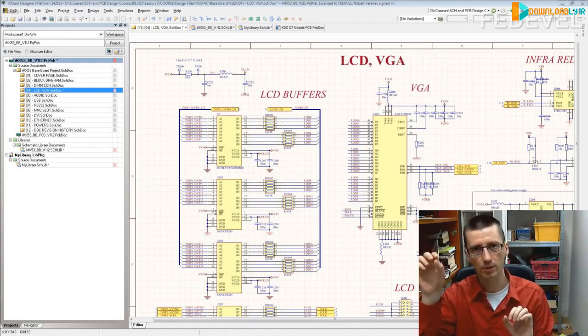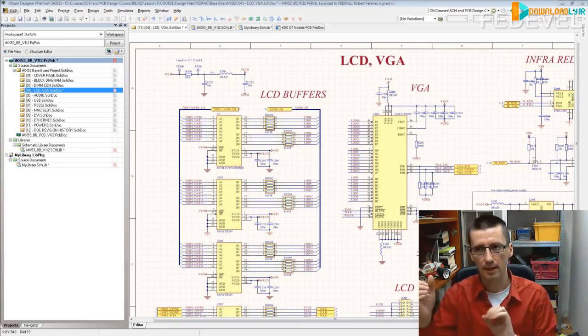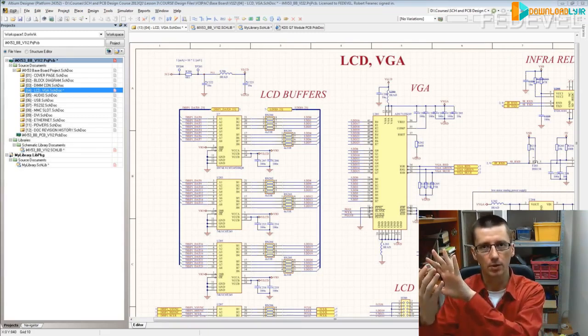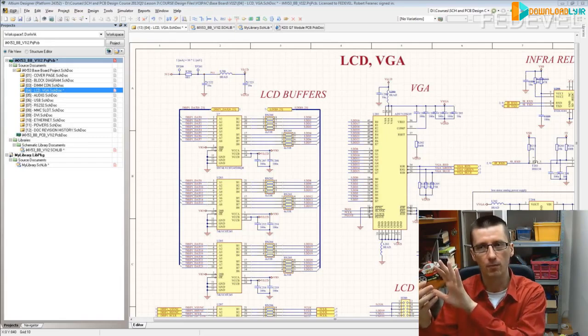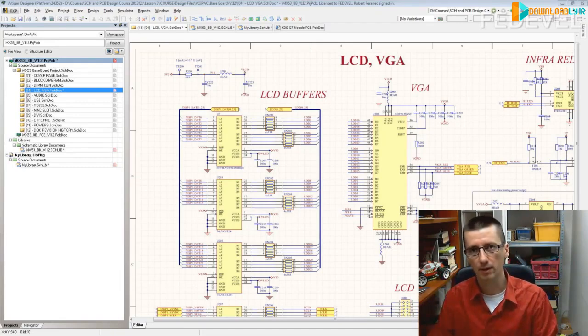I don't mix it with the digital components. And even in one of the designs, there is Ethernet on the top, for example. In another design, there is PCI Express or some other wireless cards. And audio is working perfectly, no problems. And the ground is not separated, the ground is common for the whole board.